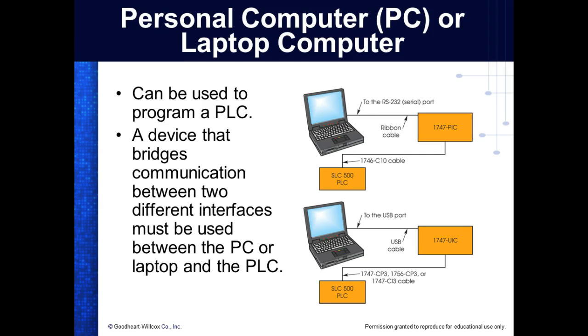Then we'll come back over here. We'll go to lab 200, and then we're going to figure out who's going to assign the PLC, and then you're going to figure out what your PLC is, what it does, how many inputs it has, how many outputs it has, whether it's sinking, whether it's sourcing, whether it's relay, and all that kind of stuff. We'll figure that out too. How many inputs does it have? How many outputs does it have? Any questions?